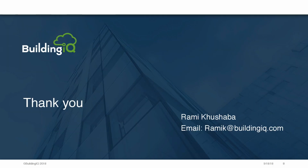Last question came in. Does BuildingIQ interface with all types of building automation systems? I can answer that one, and the answer is yes. It's a somewhat qualified yes, but a yes. We work with any building system that can output through a BACnet IP interface, or a structure-aware interface, and we have some drivers as well. But generally speaking, if your system can be output through BACnet IP, we're good to go, which means that we could potentially put a Niagara front end on it and access the BACnet data through the Niagara front end from Tridium.